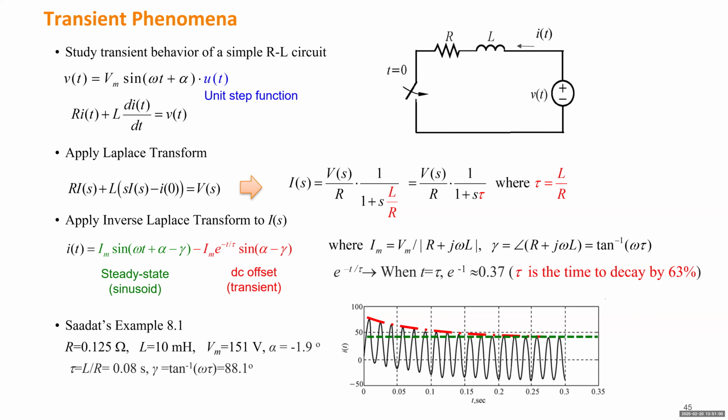And if you have many generators, you need to integrate many equations. Another way to simplify the analysis is to categorize dynamics into steady state behavior, transient dynamic, or even faster subtransient dynamic. In order to do that, we need to define some parameters, such as time constants, which tell us which dynamic we're really interested in.